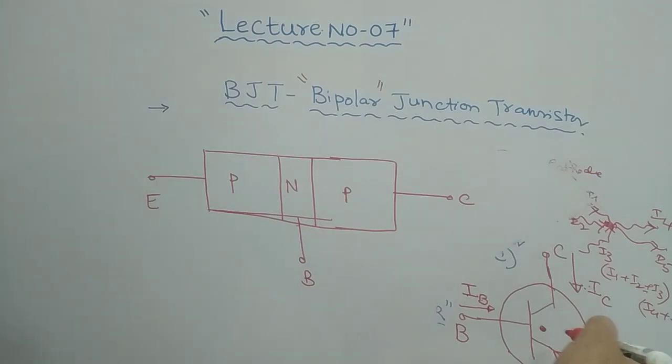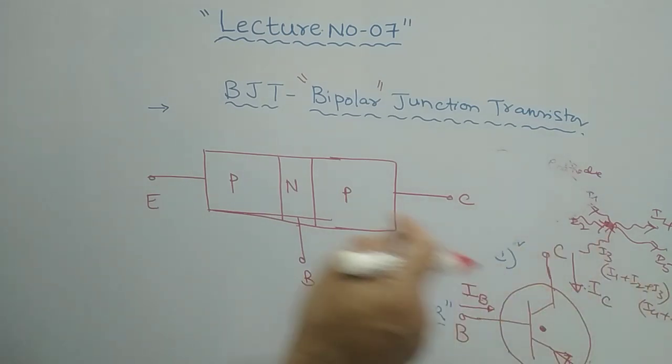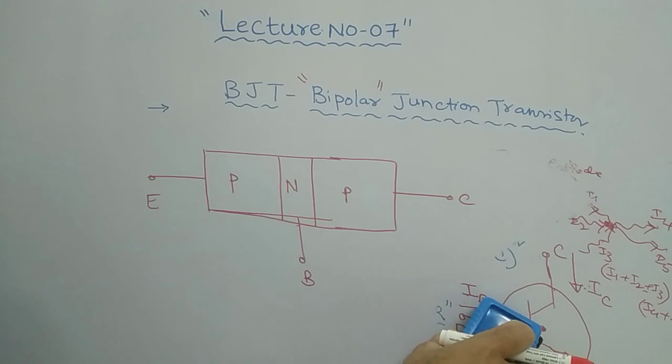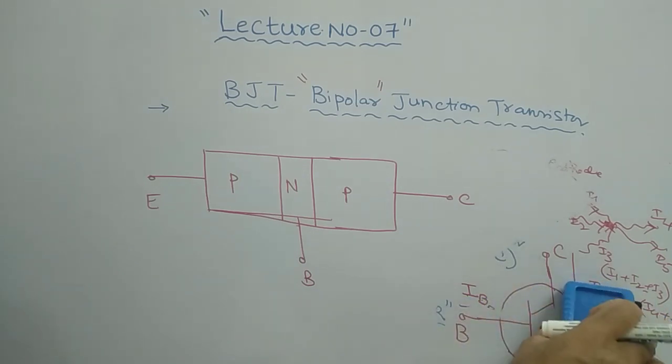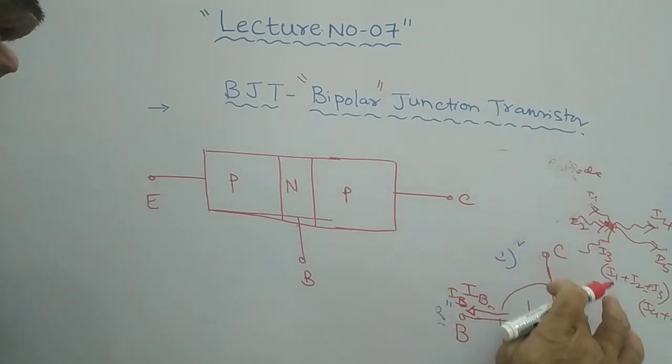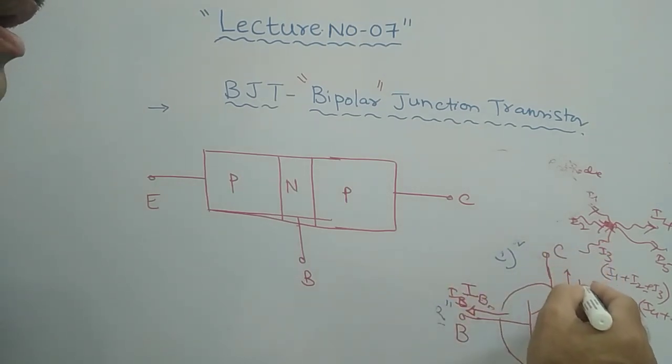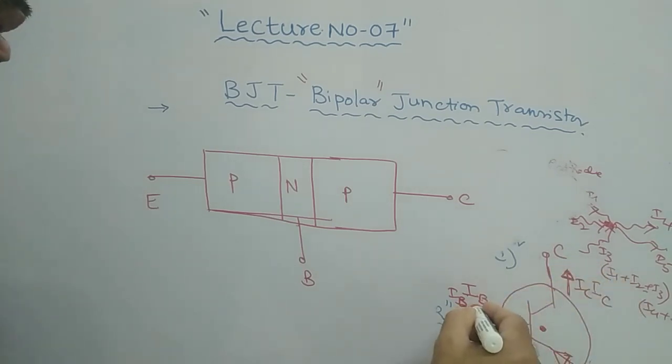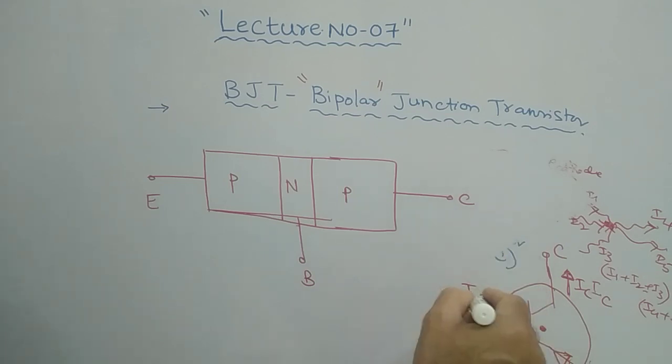Once it enters, then definitely what is the flow of the currents IB and IC? Definitely they will be shown in the backward direction, because it is entering. Therefore, entering to a node is equal to leaving. Therefore your IB should come outward, and here your IC is also going outward. You must show the reverse actually. Previously, whatever direction we have seen in NPN, you just reverse. That's it. This is what a PNP transistor is, right?